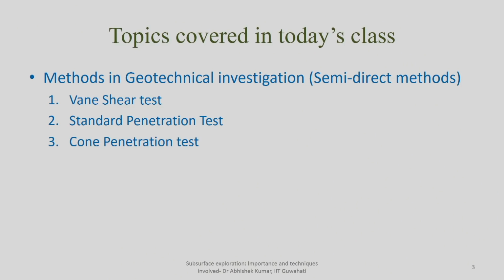Which semi-direct methods, particularly in geotechnical investigation? These are the list of some semi-direct methods. So we have the vane shear test. Many of you might have heard about this test. As the name suggests, you have some kind of vane which you put into the soil in order to understand the shear strength property.